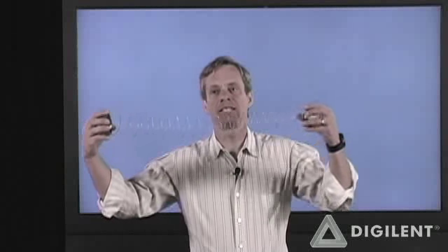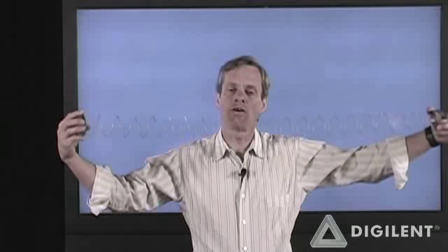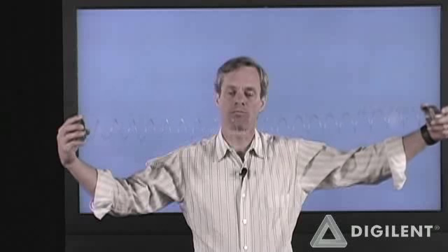My Slinky can also have a nonlinear behavior. Hooke's law is a good way to model this system if the displacement is small. If, however, I displace this a lot, the more I stretch it, the harder and harder it gets to stretch the spring. In fact, in the extreme, after I stretch this far enough so that it's uncoiled all the coils and it's a straight wire, I would have to plastically deform the wire in order to continue to stretch it anymore. That would require a lot of force just to get a little bit of displacement.